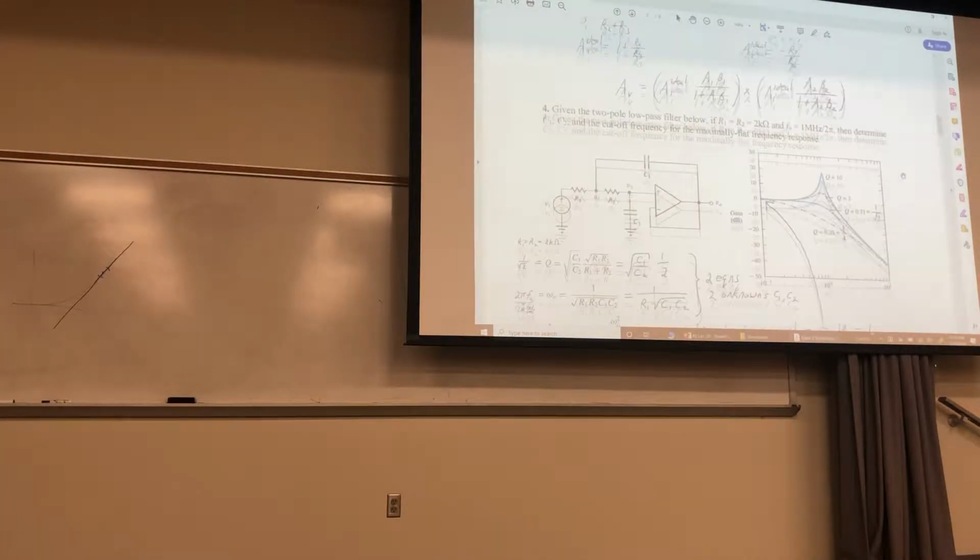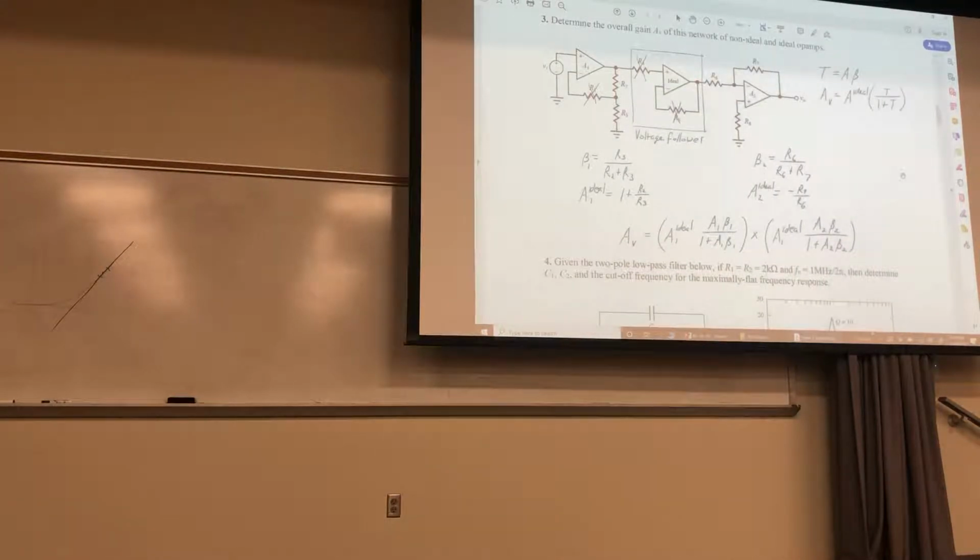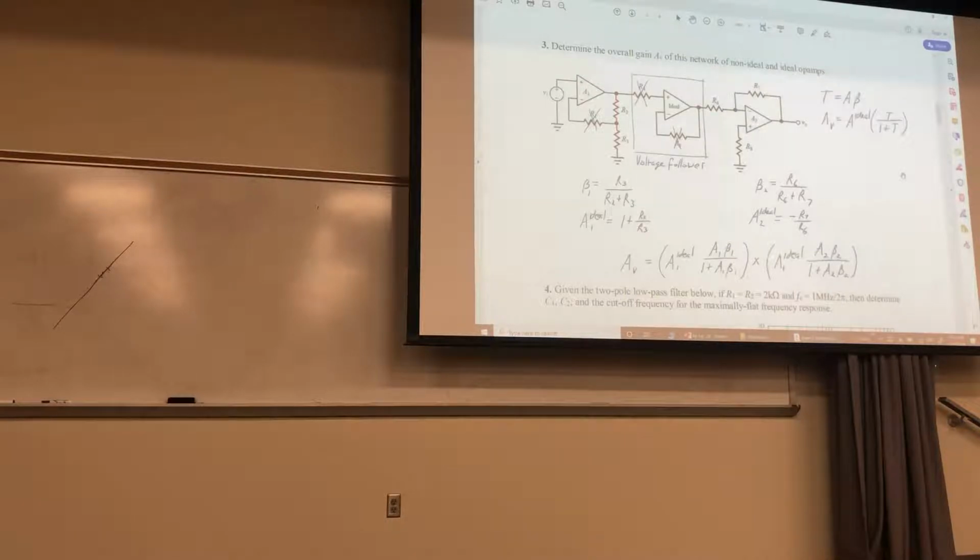What else did I see that people had a lot of trouble with? People had a lot of trouble with this right here. In the practice exam, you didn't have this, right? All you had was this and this. But this right here is a voltage follower. So no current is going through here, no current is going through there, right? This voltage is just being copied over there. Now you can have current go through here and into the nodes here, which is the same thing as the current going through over here. Now this resistor is irrelevant. I can also cross off this one too. That's irrelevant, right?